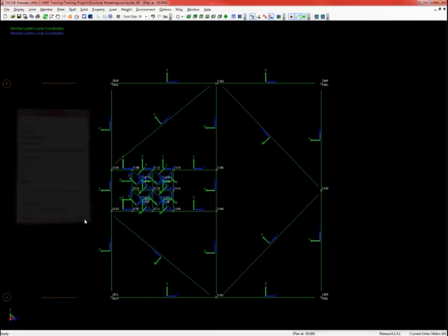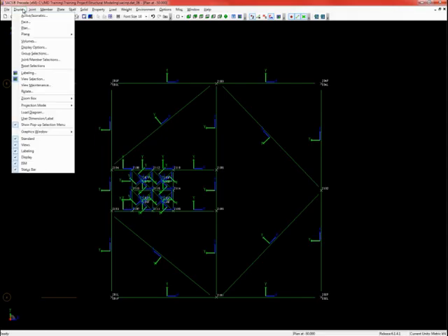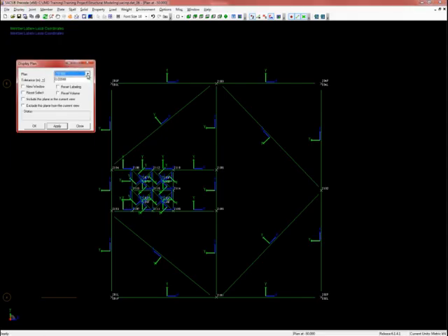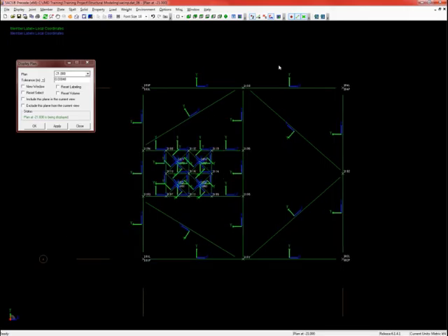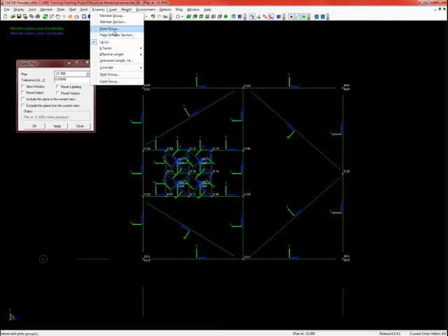Then we're going to go to the next elevation. So we'll go to plan. This will be the -21, apply. For this, we're going to use the effective length, the LY. You can use either way. You can use the KY or the LY. LY will just give you the length, where the KY gives you the factor. So for this I'll just show you the other way you could do it.